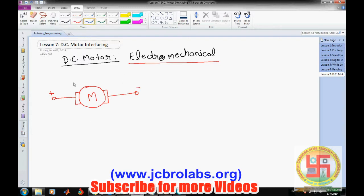Let's say if we apply a power supply of plus 5 volt here and 0 here, we can assume, let's say, it will rotate in this direction, and if we change the polarity of this supply, it will rotate in the opposite direction. This should be known, why we are saying it is rotating in one direction, opposite direction, because just by looking at this DC motor, we will not know whether it will rotate in a forward direction or a backward direction.